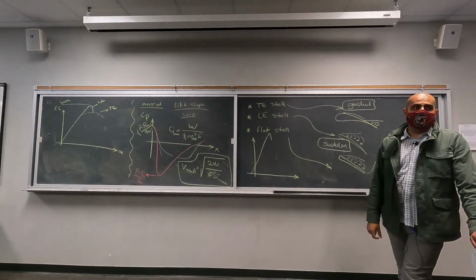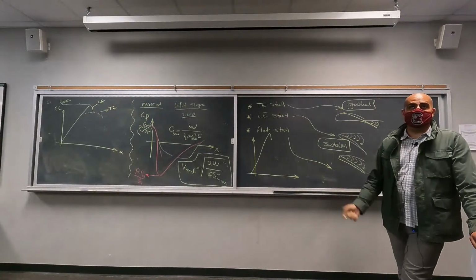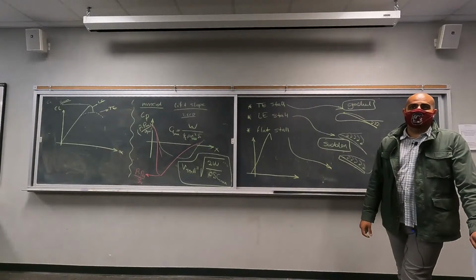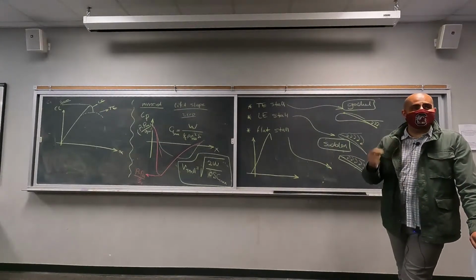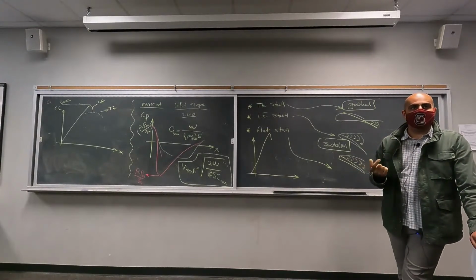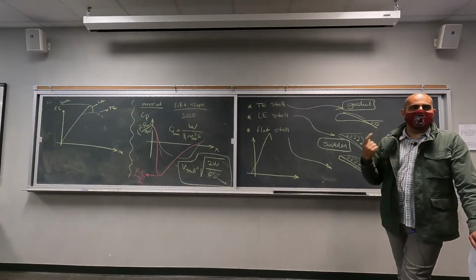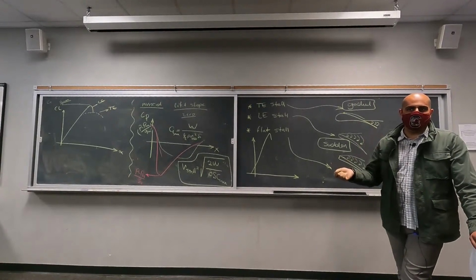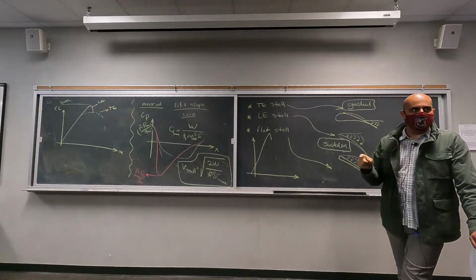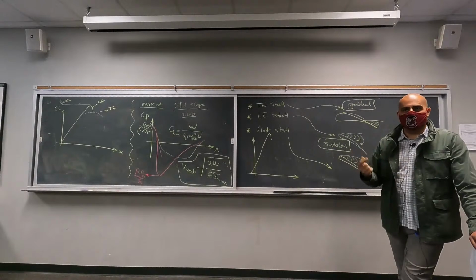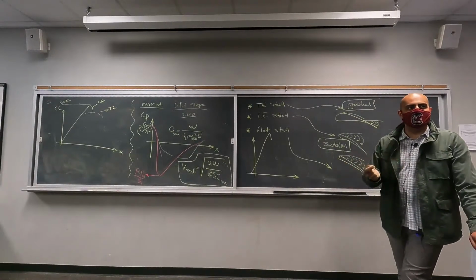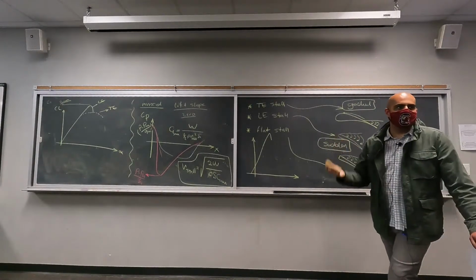Sharp edges, right? What do sharp edges do? They are going to facilitate the separation. The separation doesn't really happen, I mean, it happens because of the adverse pressure gradient, but your sharp corners are going to be helping the flow separation. We had a discussion about tipping the flow to turbulence, right? So you have some sort of a mechanism there on your airfoil to tip the flow. These sharp corners are tipping the flow to separation, if you will, okay?